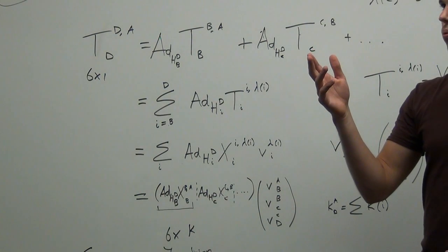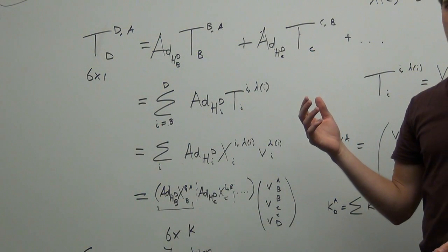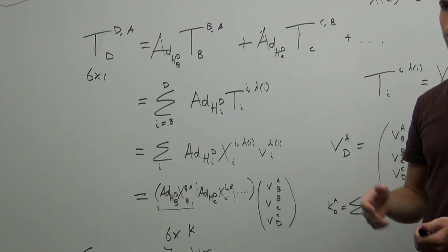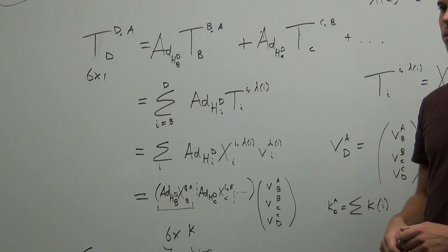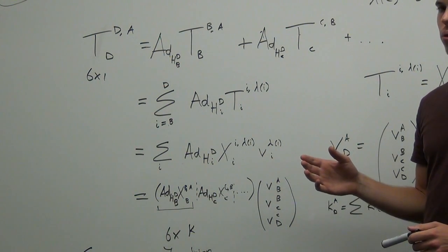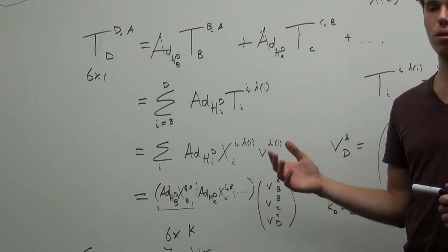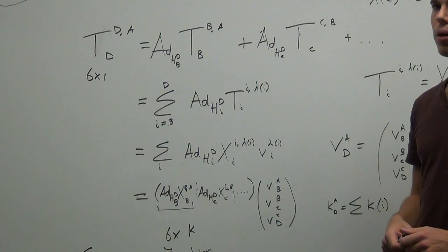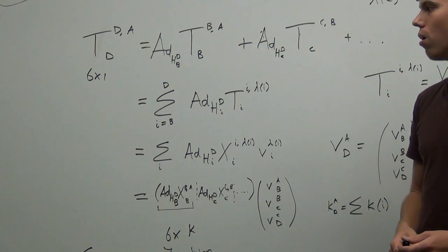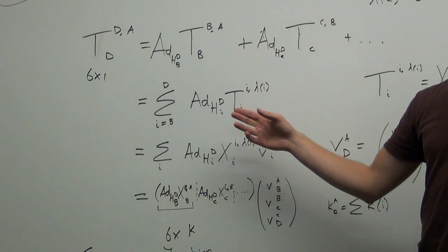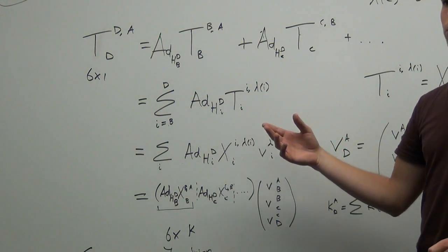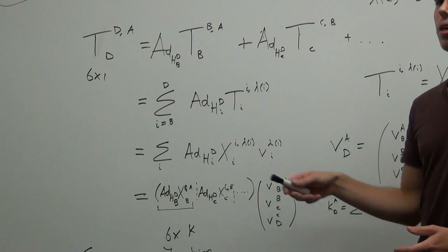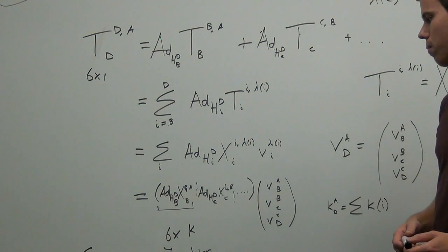And in our code, with the whole reference frame structure, that's the first thing we do. Once we've set all of the joint angles in the joints that we've measured, we call update frames, and then all of those local transforms will be calculated, and even the ones to world, lazily.